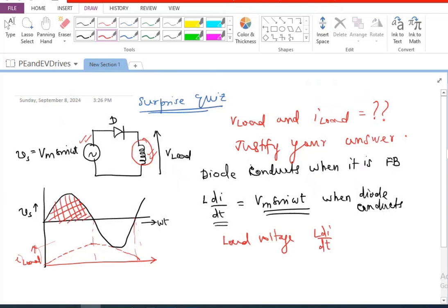After the end of the positive half cycle, because the current is at its peak value, the inductance is definitely going to release its energy. When it is releasing its energy, it will be actually plus here and minus here. So there will be something like a tug of war between the plus voltage of the inductance and, because we are talking about the negative half cycle now, the plus voltage of the supply also.